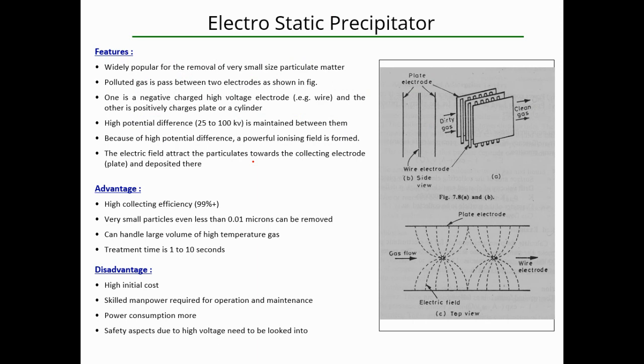Okay, next comes the electrostatic precipitator. This is also a mechanism for collecting dust particles, but in this case there is a small difference. If the dust particles are charged particles, then they cannot be removed just by a bag filter, due to the particular charge on the particles.